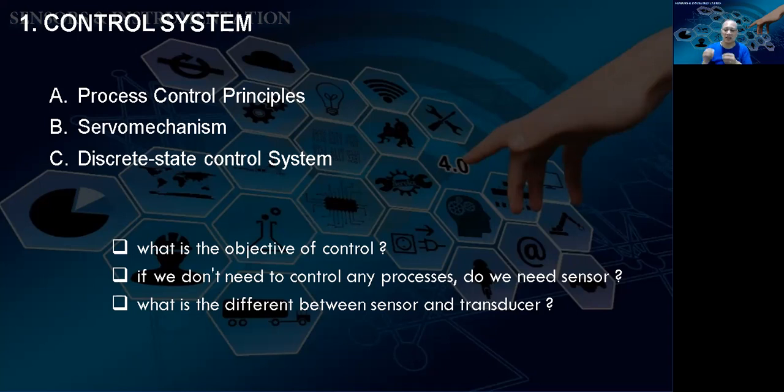So when we talk about sensors, it is sensing physical phenomena, physical changes, like temperature. When you use a thermocouple, there are some physical changes in the material that is the thermocouple. Or if you're using a resistance temperature detector, RTD, then the resistance changes due to temperature. So physical to physical, but if you combine it with some instrumentation like a Wheatstone bridge, and transform the signal from physical to electronic signal, then it becomes a transducer. Basically, for lack of a better definition, a transducer is more complex than a sensor, because it has some mechanism of transforming energy like that.